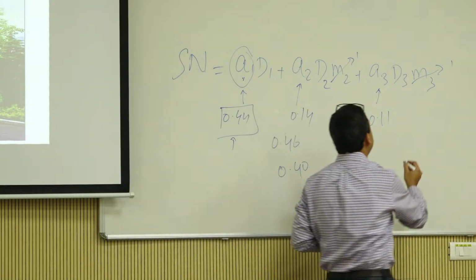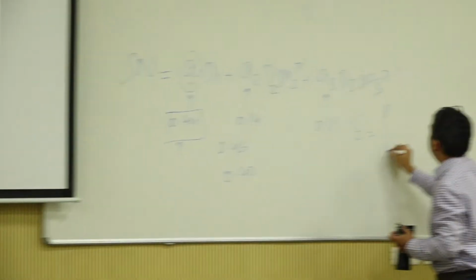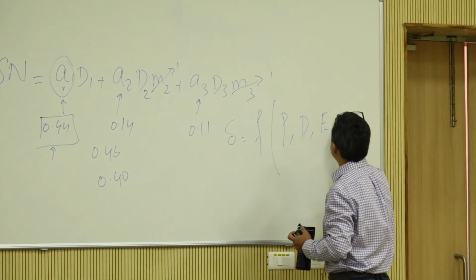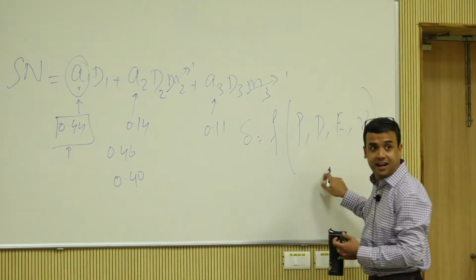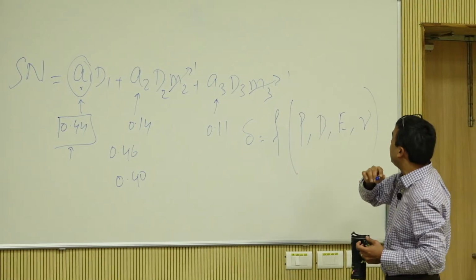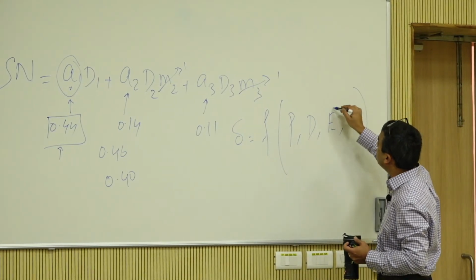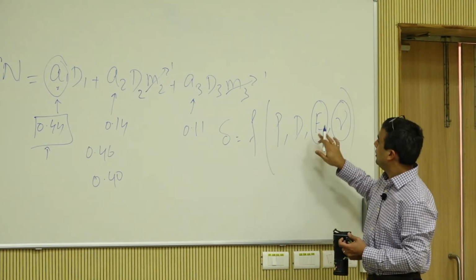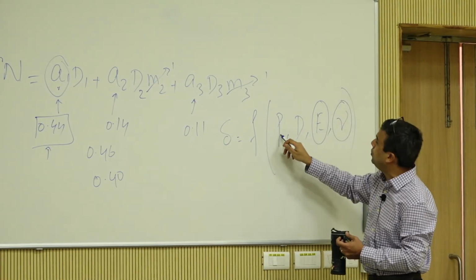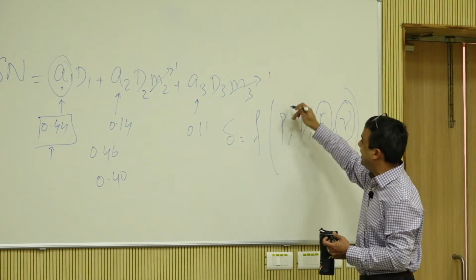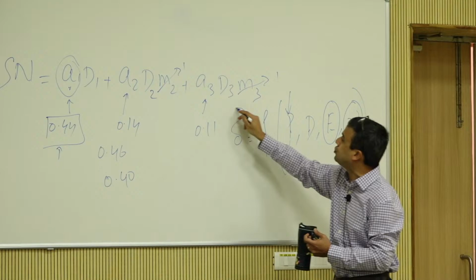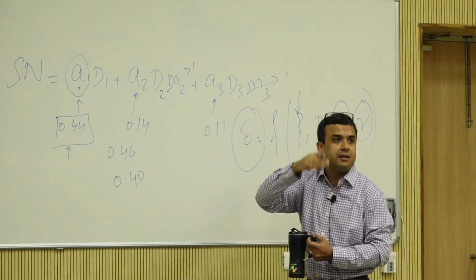In mechanistic, what did I say? Delta is equal to a function of load, thickness, modulus and Poisson's ratio, I said, right? So the material that you're studying, your PG grading and everything, is contributing to this and this. So you determine these and then you do this and this. This is known already, this is the demand. The D is what you determine so that your delta is in a stable range.